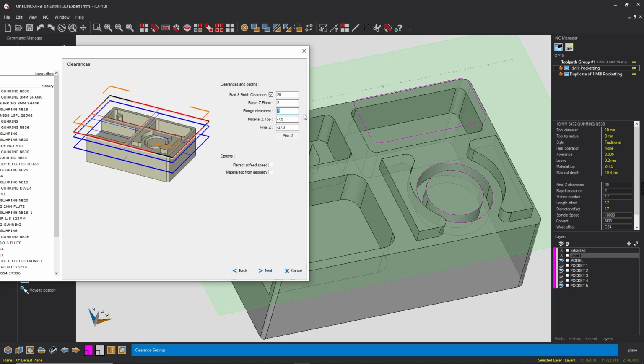My tool will start at Z minus 5.5, and then it will heli mill, plunge, or ramp down from there. So admittedly I'm going to do 2 mil of fresh air, and then it will start cutting material. If you're really trying to dial in that cycle time, then have minimal clearances. So the way that program's going to come out, it's going to go Z20, it's going to go Z2, coolant's going to come on, it's going to dwell, then it's going to feed down to that, I believe. It might rapid down to that actually. Then it will feed from that number down basically. But I think that will be a rapid movement.